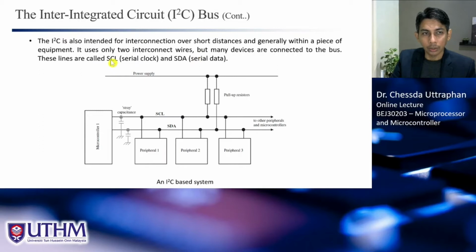The clock is called SCL, or serial clock, and the data is SDA, or serial data. And this is the bus that connects to the peripherals, and of course all the peripherals share the same bus, just like in SPI.